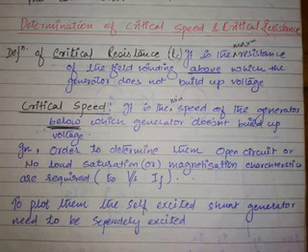If you see the EMF equation in the generator, you have written Eg as the induced EMF. If you remember this Eg, when you connect some load, let it be Eg. If there is no load across the armature, no load means the armature is just open. So let the voltage in the armature be E0. What is the difference between E0 and Eg? You will understand after the discussion of armature reaction. So, the no load induced EMF versus field current. You want to plot this particular characteristic in order to determine the critical resistance and critical speed of the given generator.